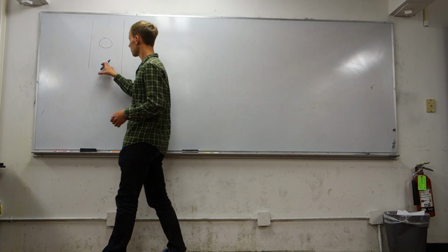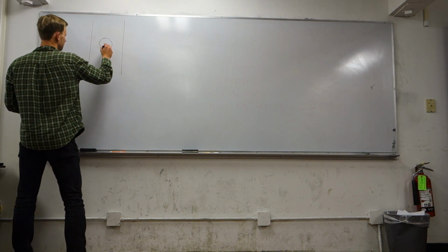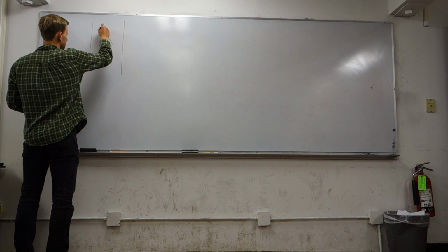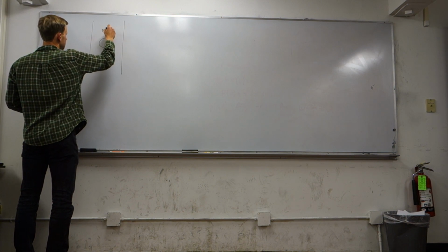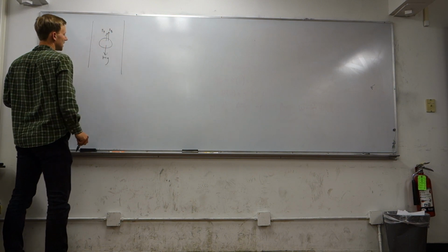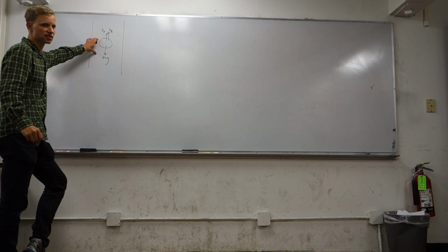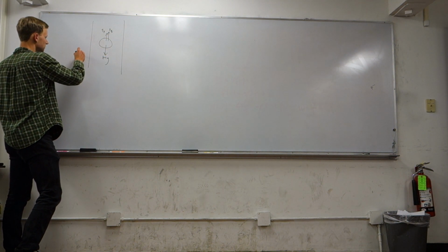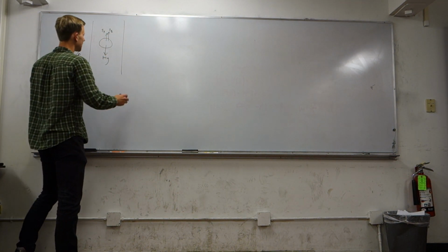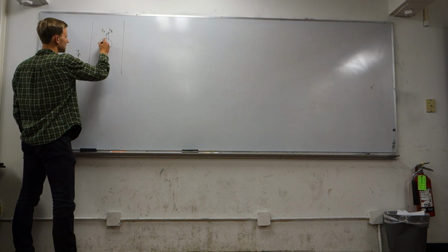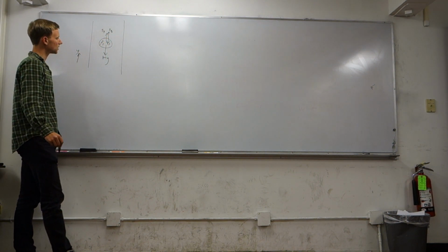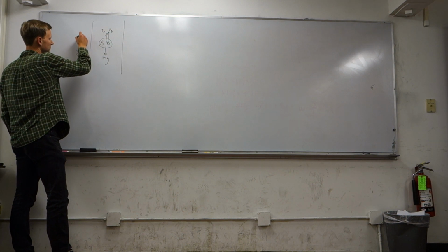So let's just draw a free body diagram for this body. It's going to be some gravity force, it's going to be some drag force, and there's going to be some buoyant force. And we're going to say this thing has reached steady state, so it's going to be non-accelerating. And we can define our coordinate system with y going upward. And let's say we know the density of the sphere and the volume of the sphere and the diameter of the sphere.